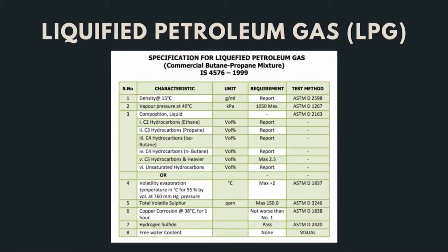So now let's try to understand the different specifications for LPG. Here an exhaustive list is given. These are all the different kinds of specifications for LPG, but today I am going to talk only about some of the key things. Here the vapor pressure is an important specification because if vapor pressure is more, then the storage and handling of LPG will be difficult.